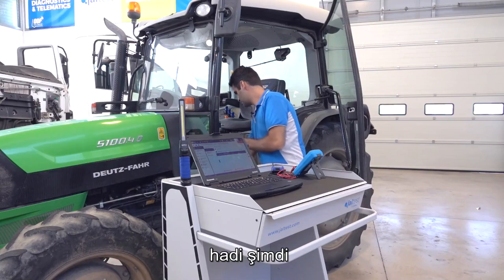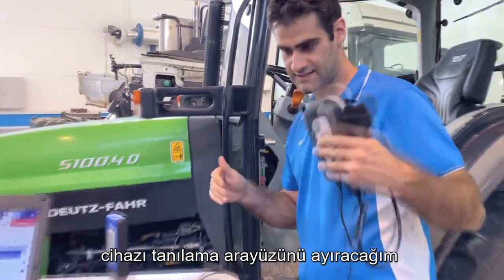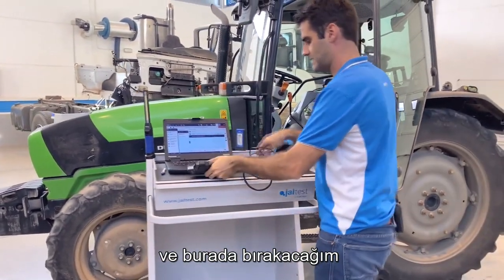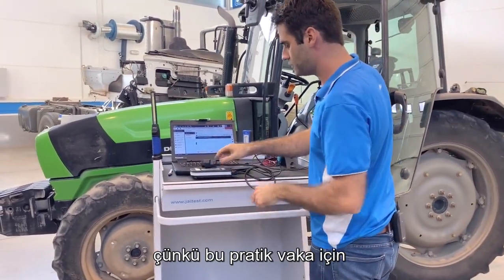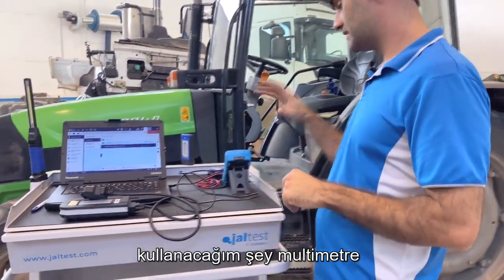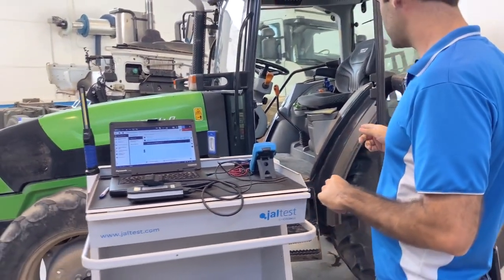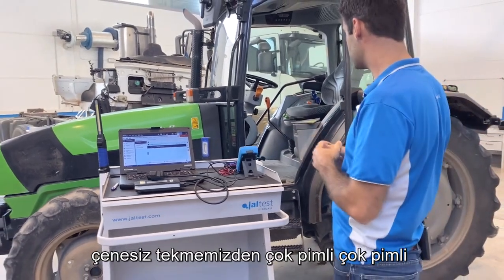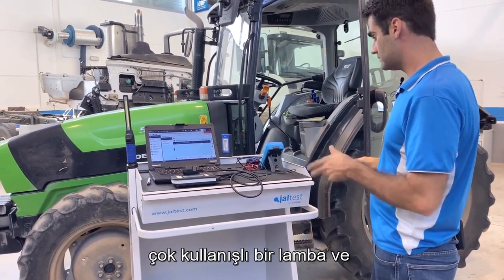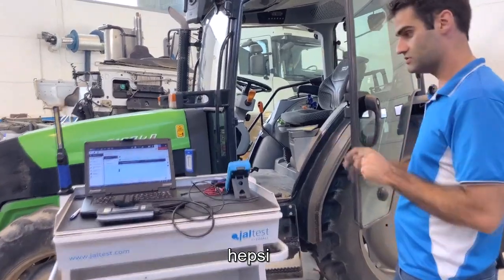So now I'm going to disconnect the diagnosis device, the diagnosis interface, and leave it here, because for the second part of the practical case, I'm not going to use it. What I'm going to use is the multimeter, some multi-pins from our Jaltest kit, which is very useful, and one lamp to check out the diagnosis connector, and that's pretty much all.